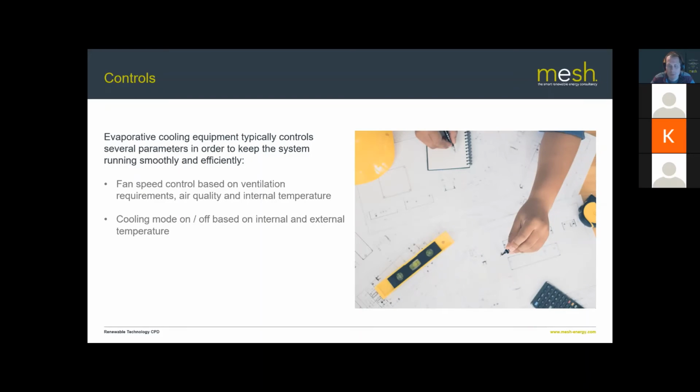So the answer to your question is it would depend on what other mitigation you had in there for the dust. Assuming you're collecting that dust through some sort of local exhaust ventilation system, you should be able to use evaporative cooling for the supply air, because obviously any air that you're taking out of the building, you need to be replacing anyway, and probably your supply air requirement is going to be the limiting factor there. So I hope that answers your question, Patrick.